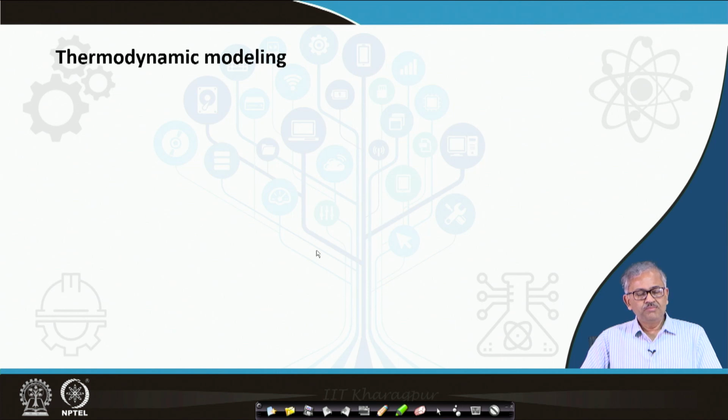What do we mean by thermodynamic modeling? As the name suggests, you assume the reactor is in thermodynamic equilibrium. Then you can apply a thermodynamic database like FactSage and calculate the output, the phase constituents at equilibrium, the temperature, and the heat of reaction. All these things are possible. So basically a thermodynamic model can capture the saturation level of the product.